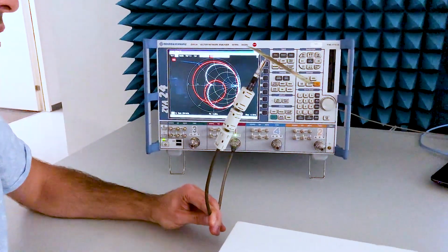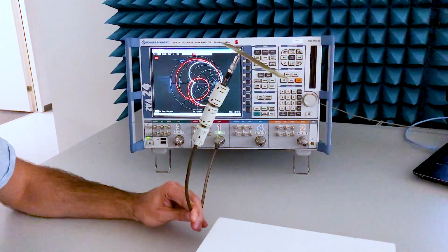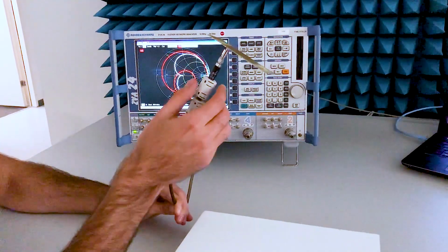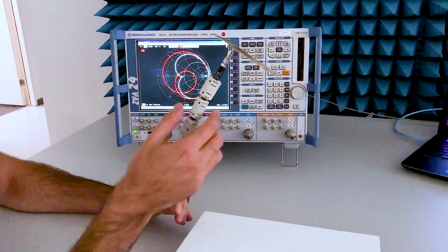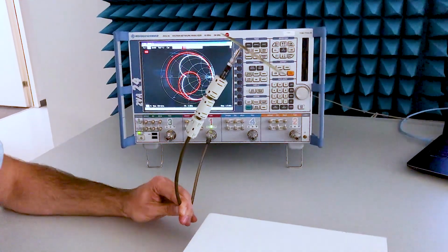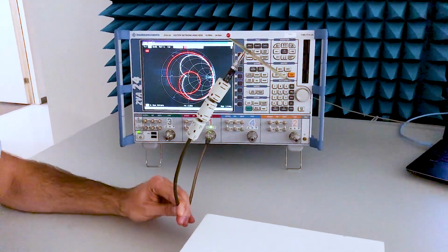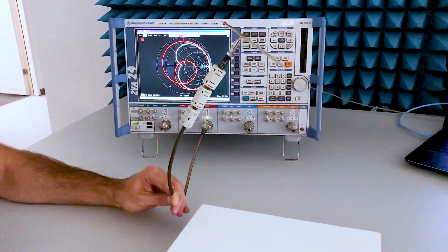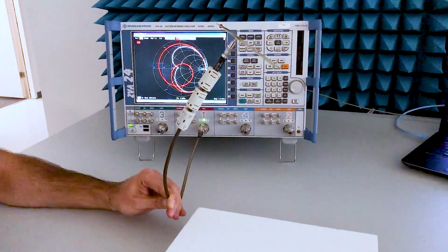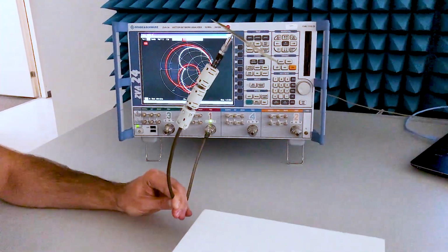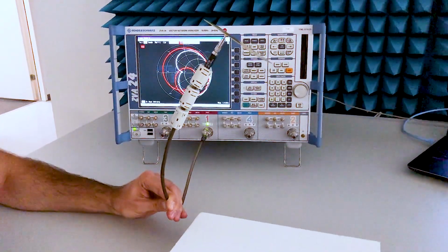Now we have the ferrites on and the effect of the cable currents is less visible. Look, when I touch the cable, not so much changes in the Smith chart. But the problem is that the overall result still looks very different from the target. So that's probably because the cable becomes an element of the electrically small antenna, adding a boundary condition and changing the result compared to the measurement, which is fully isolated. Shall we use the optical head for VNA and measure it?